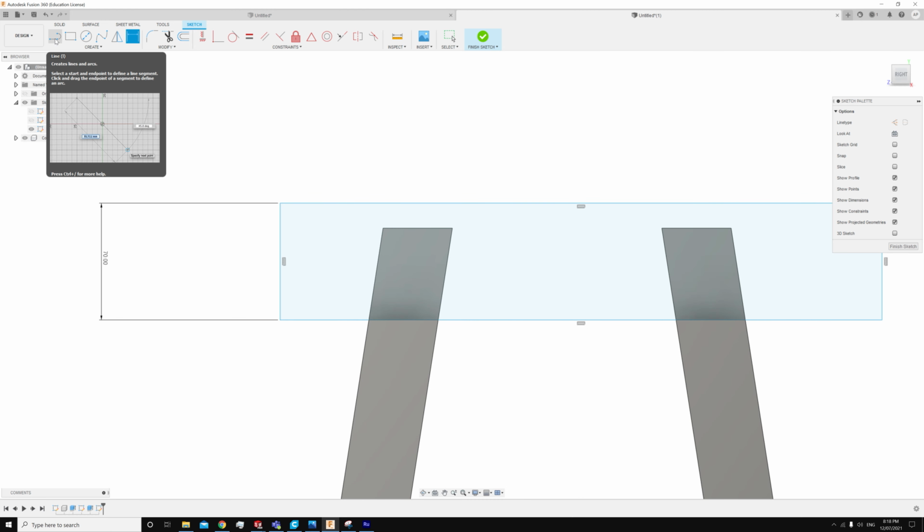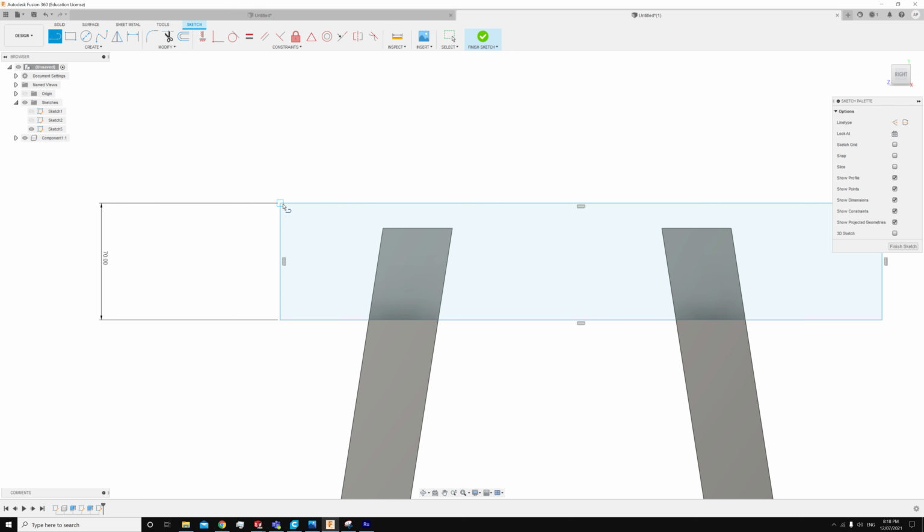Additionally, we have some slats made of spotted gum for the seat, which are 80 by 18 millimeters, which are dressed all round. And so it's going to be important that the edge section is just around or a little bit over 80 millimeters so that those slats can actually fit on there properly.